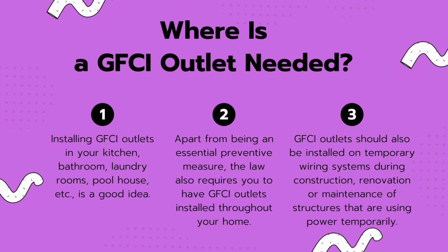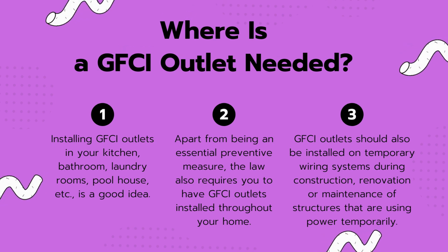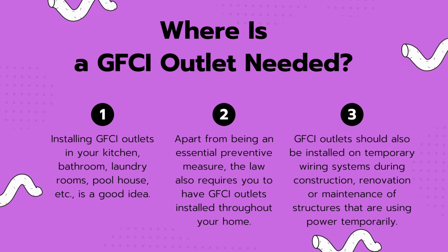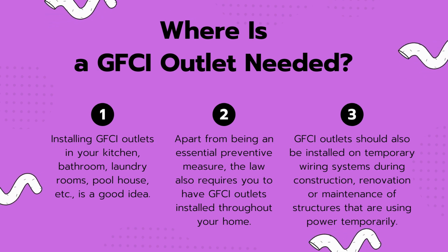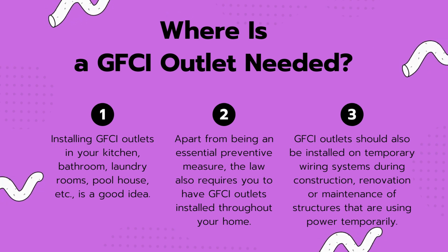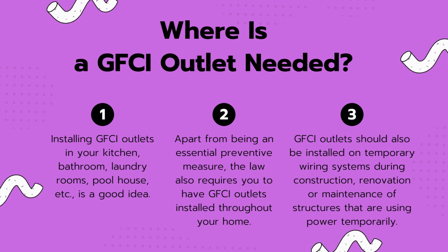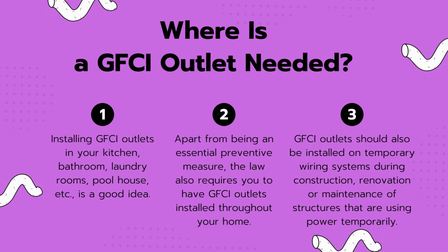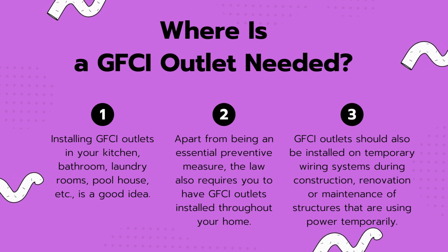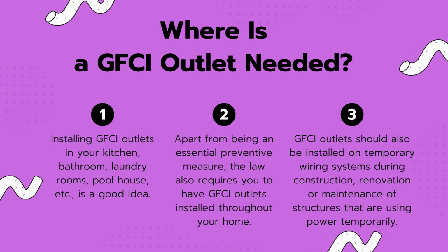Apart from being an essential preventive measure, the law also requires you to have GFCI outlets installed throughout your home. According to the National Electric Code or the NEC, all homes must be equipped with GFCI protection. A GFCI outlet should also be installed on temporary wiring systems during construction, renovation, or maintenance of structures that are using power temporarily.